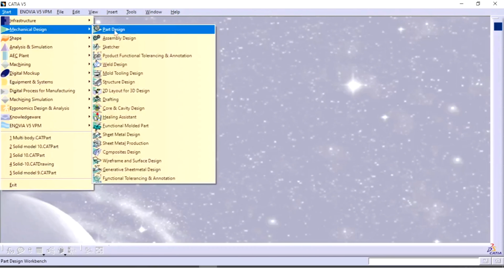So now how will we use the Boolean operation add? This command merges one body with another. How to use that? Click on the body which will be added to the parent body. This will be the parent body. Now in body 2, right click, go to body object and then add.